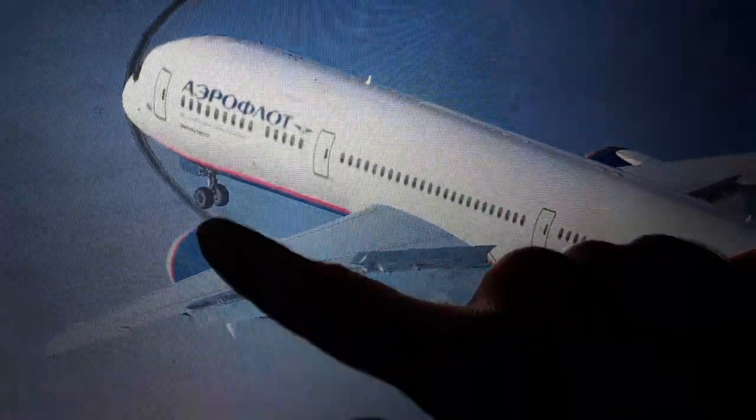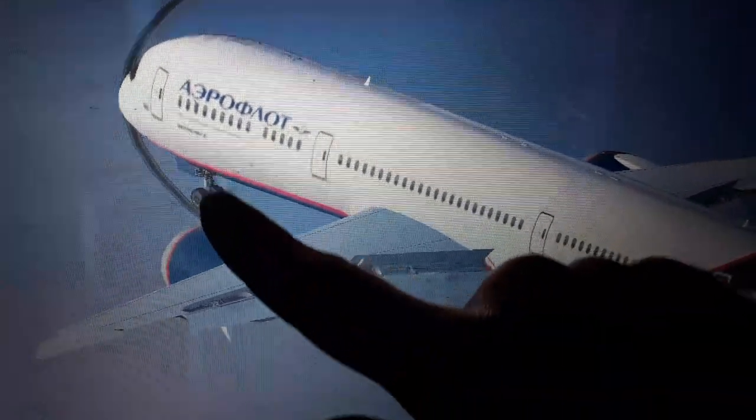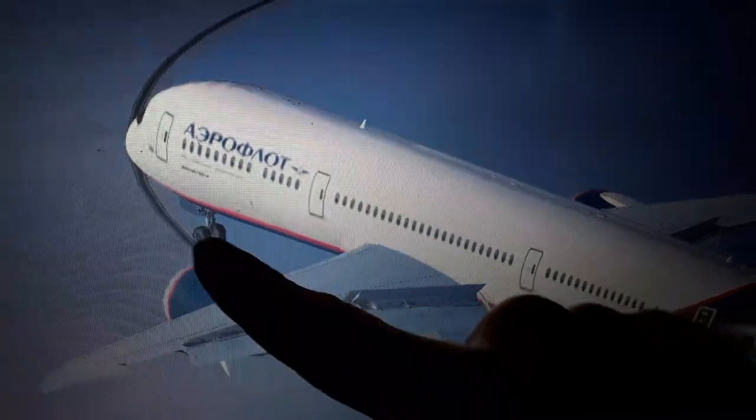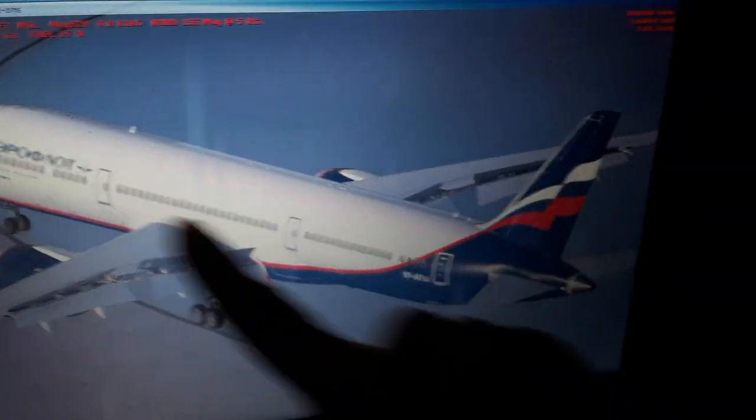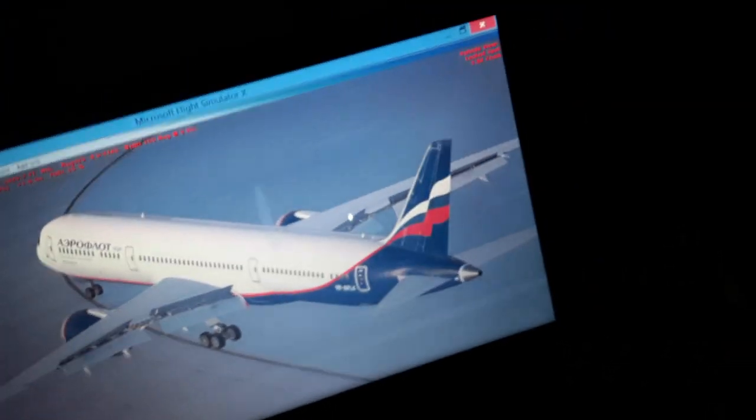So the nose will steer. You can see we have the forward nose wheel over here. It deflects with the rudder pedals or the tiller 76 degrees left and right, from 0 knots up to 45 knots. We have the rudder then coming in, aerodynamically effective from 45 knots, nautical miles per hour, in takeoff or in landing.